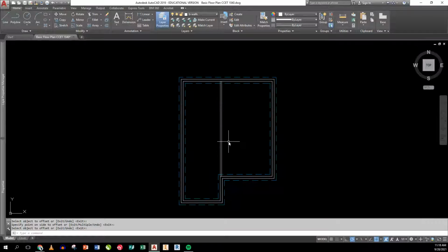Now, because it's a bearing wall in my basement, I have to have a footing. Notice I've got a greater distance to the right side here than I do to the left. That's because, honestly, I want to have few weird corners in my basement, and this is a normal spot to put one. And 17 feet of span for a normal floor joist is no big deal, okay? And this is only 13 feet of span, so it's an asymmetrical span. But in reality, I'm going to order 30-foot joists, and I'm going to strand them all the way across. This is just to make it so they don't get saggy out here in the middle, okay?